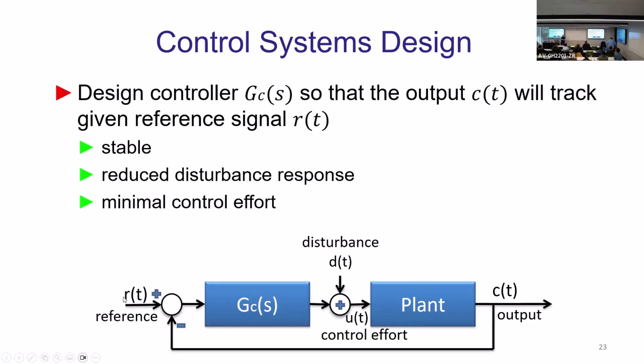And frankly, I hate that notation in the textbook, Y, C. Like output needs to be Y, not C. I don't know why they call it C. C is controller. Whatever. So the output needs to be as close as possible to R. This is the goal of any control system, right? You're designing a controller, G of C, such that the signals will be such that C will be equal to R as much as possible. They will never be exactly equal, but that's what you want. Any objections to that kind of idea of control systems in general?